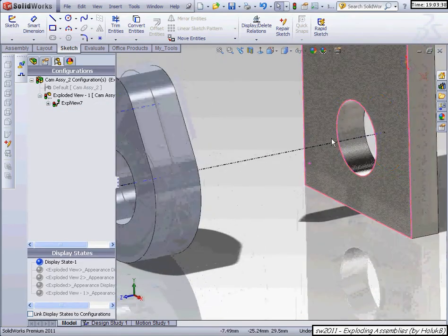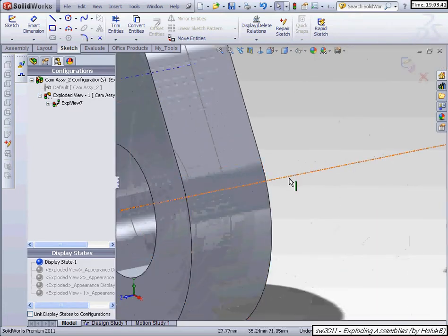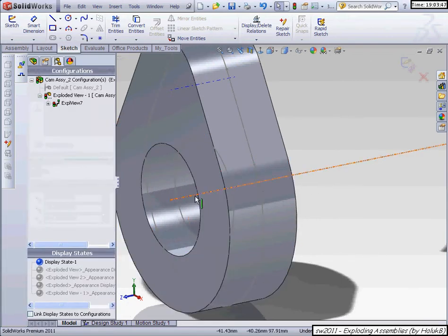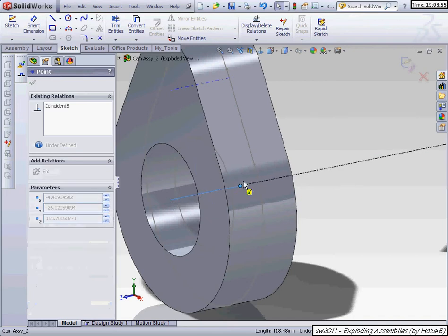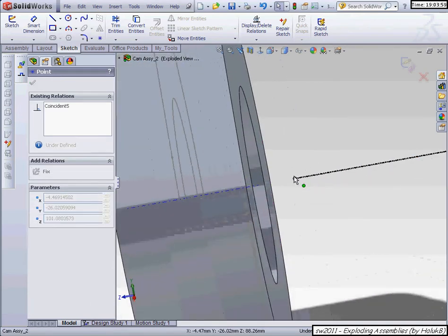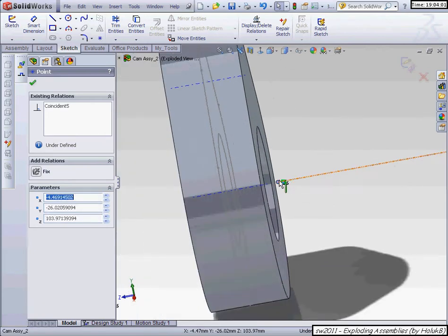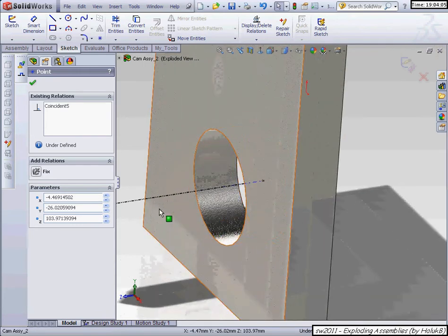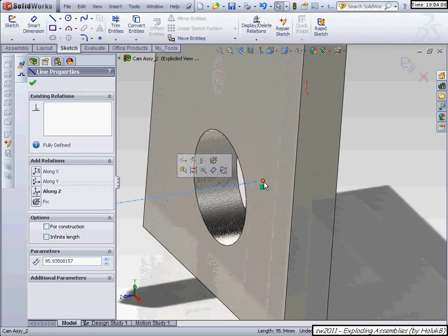And now I'm still in the sketch, see, I can do this. I can move this point here by deleting my coincidences and moving it here like this. You don't have to go into it. I'll do the same thing on the other side. I will just move this.